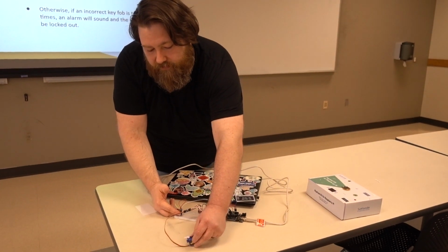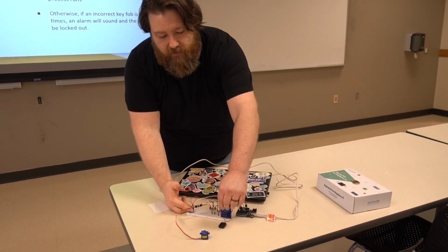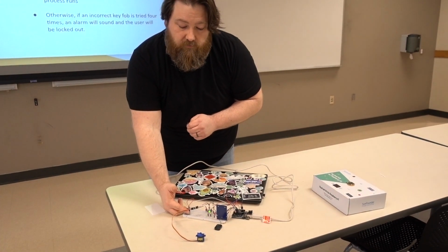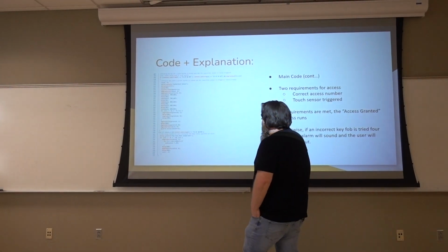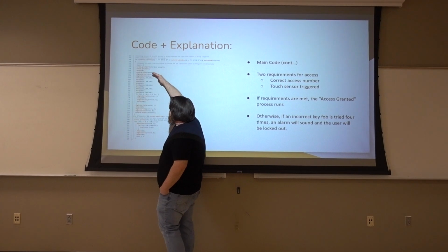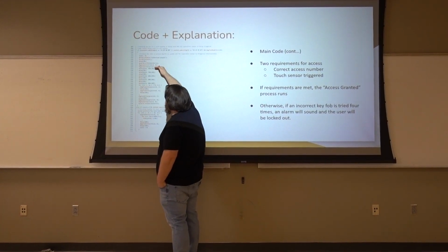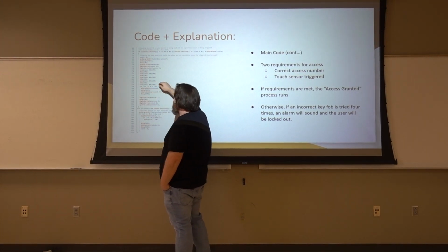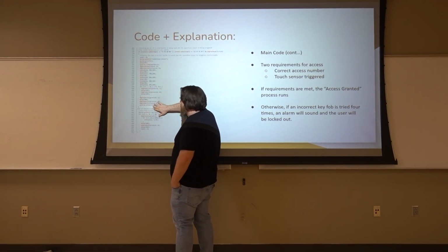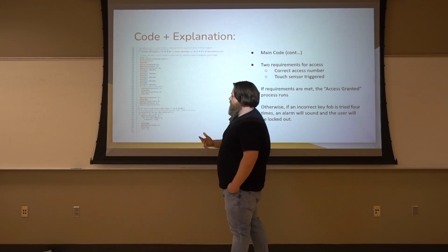And it'll actually open this servo. And after a predetermined amount of time, it'll automatically close. So that whole process is this section of code right here. So it opens, it lets you know, it gives you the tone where you've gained access, then it'll flash, then it'll come back down here and then close the servo. That's your automatic roll-off process behind you.